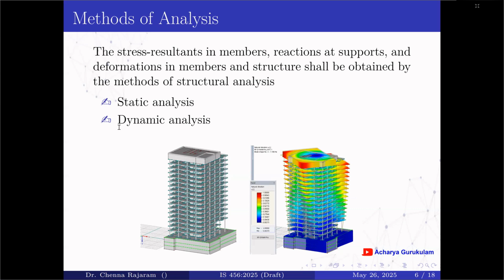The following methods of static analysis shall be considered: 3-dimensional linear static analysis in all structures. 2-dimensional linear static analysis may be sufficient in regular structures with direct load paths in the form of regular structural grid along all 3 directions, and simplified estimates may be used in limited cases as specified otherwise.